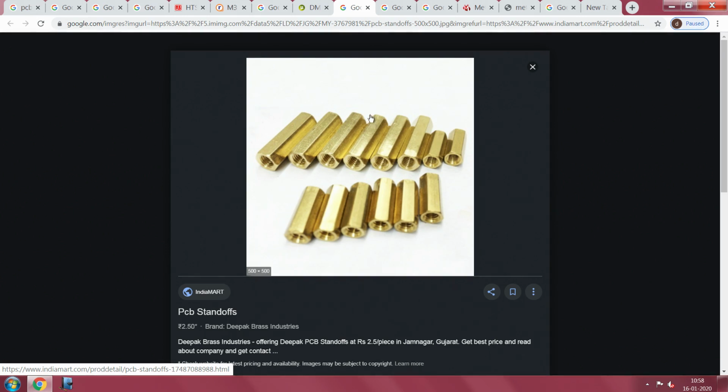They do not soften at, let us say, 80 or 90 degrees. All other things, especially nylon and all that, just at about 80 or 90 degrees, they soften, and usually the threads may misbehave. If they are already under stress, they weld fully, and later on it is a problem.